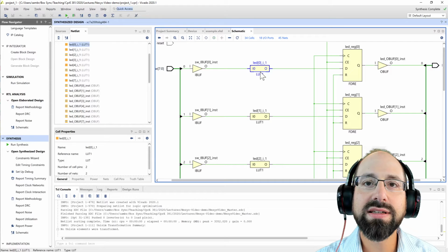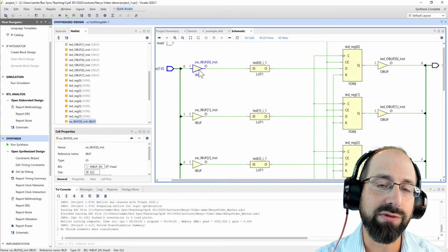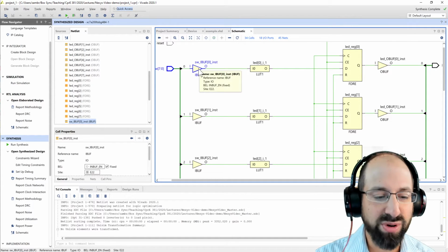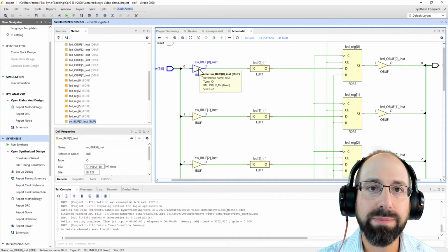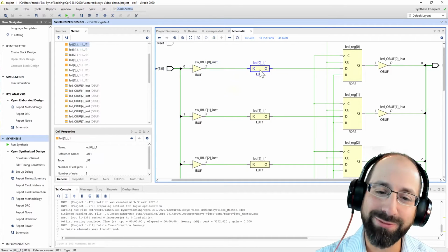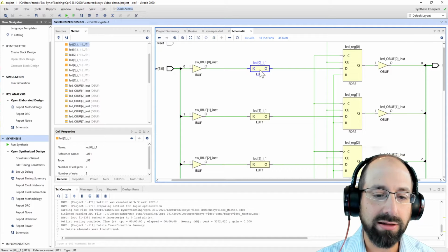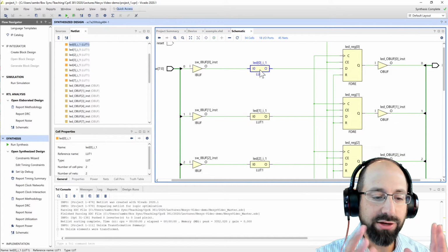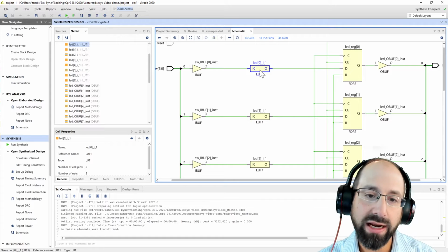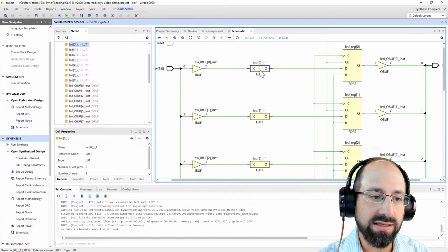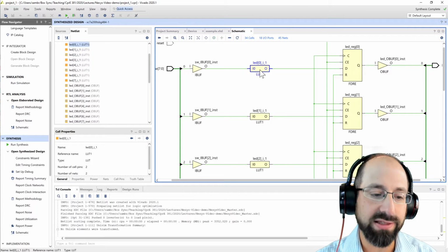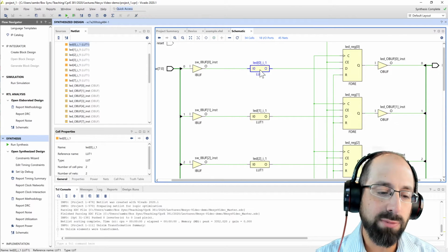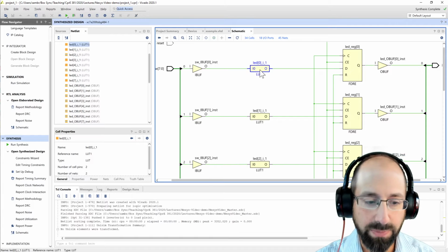Here is actually, that's not the inverter. It looks like it, but it's not. That is an input buffer to actually grab the input from the pin on the chip. This is the actual inverter now. Now it's mapping to something called a lookup table, and I don't know how much that was covered in 281. But the lookup table is the fundamental underlying computing primitive for these FPGAs. It's a small SRAM memory. The size of it depends on the device that you're targeting.